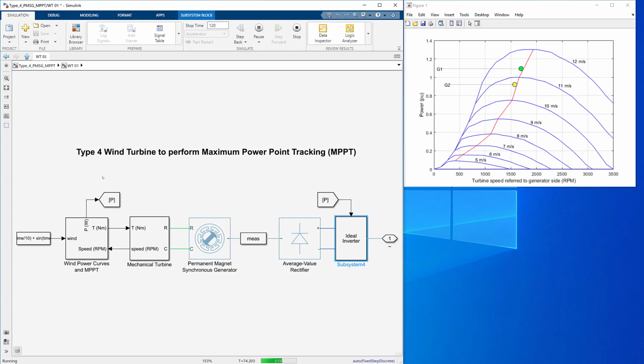But for system-level wind turbine design, we may have many turbines in the network connected to the grid, and we generally are interested in like a 1 year simulation. So this model will take a long time to finish a 1 year simulation because it captures the dynamics in millisecond level. So this is a functional design model.